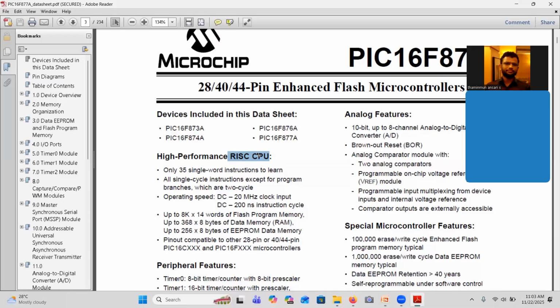Probably these 256 bytes can be used to store DTCs, diagnostic trouble codes, or some sort of system status. Those are permanent. If the vehicle comes to the service center, they can erase it using an electrical signal.